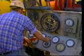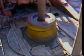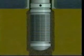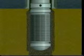Almost every phase of drilling and completing the pay zone will affect the success of a gravel pack. Basically, current methods of gravel packing are based on the principles of retention-type filtering. This kind of filtering does not allow mixing of formation sand with the gravel pack material, and, in the case of internal gravel packs, prevents sand encroachment into the perforation tunnels.